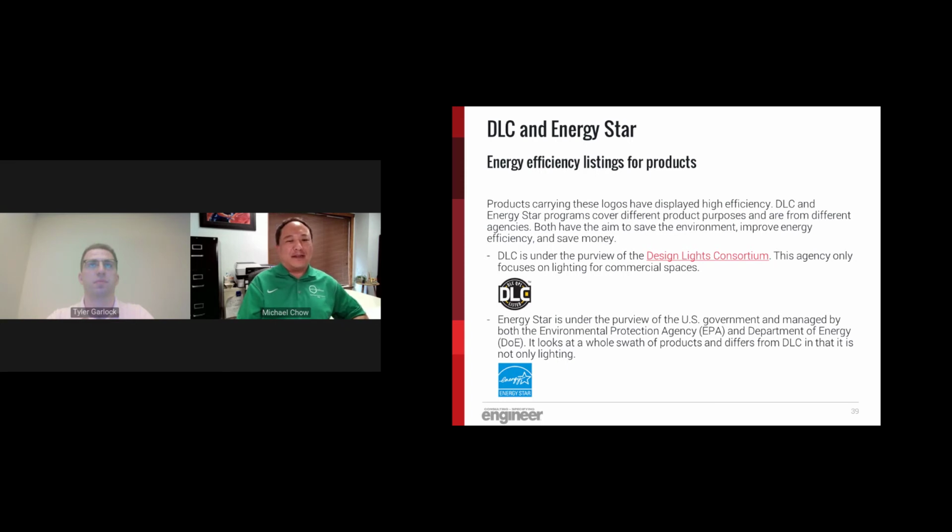Now, we had something kind of odd happen to us where we specified a basis of design DLC luminaire, and by the time it went out to bid and award to a contractor, DLC had revoked that particular luminaire certification. So it's important, I found out, to check the certification all the way through the process to make sure that something like that doesn't happen. Tyler, do you want to talk about Energy Star next?